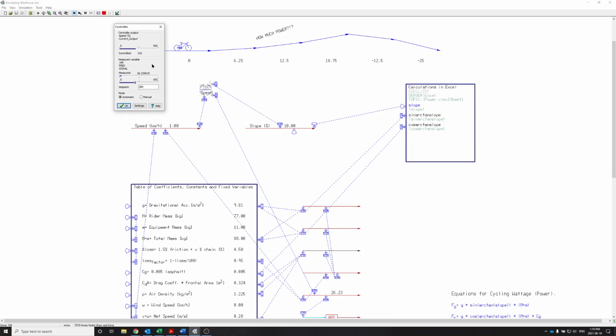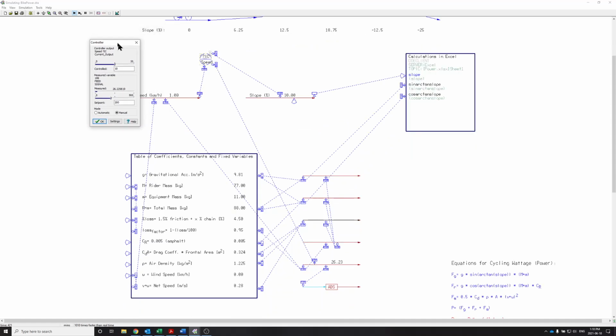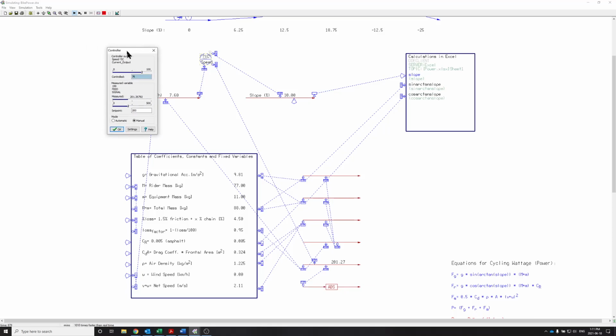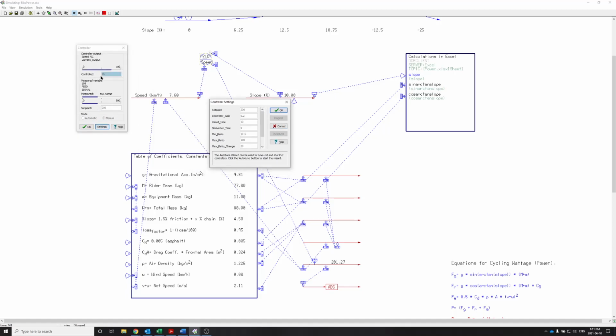Presently, it's whacking back and forth. So let's put it in manual, and we will control manually to our set point, see what that current output should be. So we're close. And then if we go to settings and we use auto tune from here on out